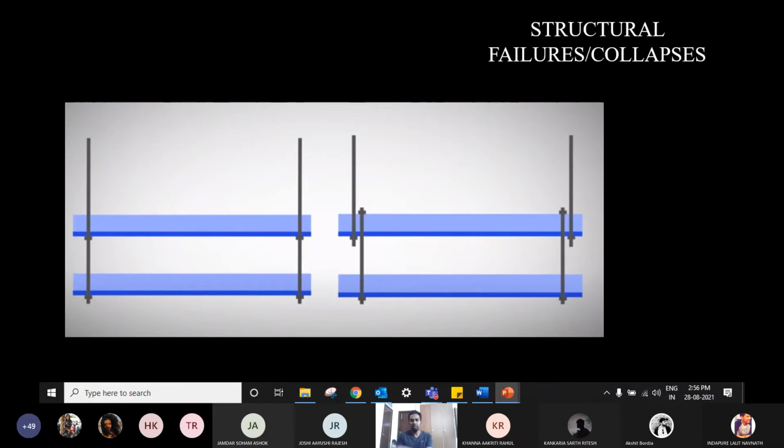In order to make individual drawings so that you can take them to the fabrication factory and build the components accordingly, you make something called shop drawings or fabrication drawings. That is the responsibility of the contractor or the sub agency he has hired to make shop drawings. During the production of the shop drawing, the contractor gave this kind of an alternative proposal.